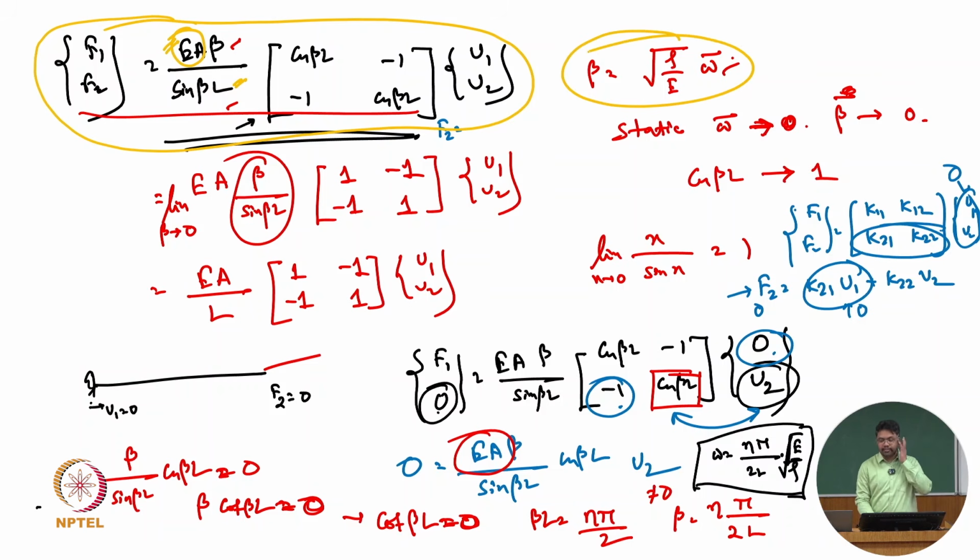So beta has your mass, the rho term is there, Young's modulus is coming in the beta, as well as your excitation frequency. So that full thing is fused into a single parameter beta. Therefore this type of dynamic stiffness matrix is known as the spectral element matrix, because you cannot directly get what is mass, what is stiffness.